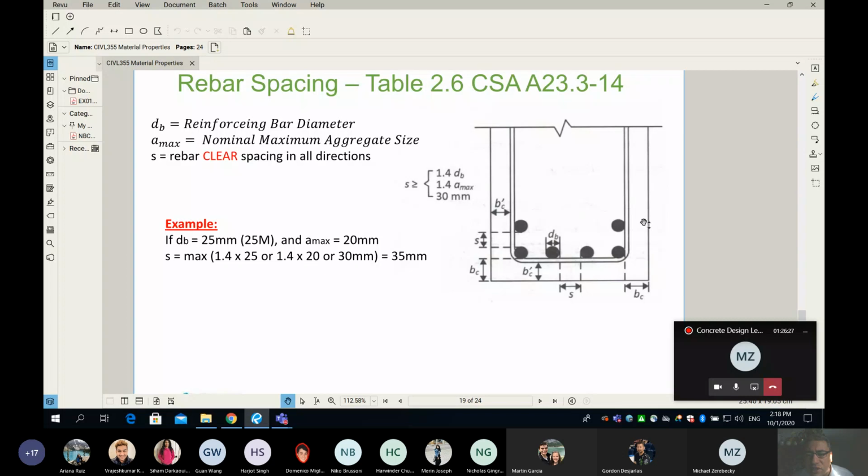When we bundle the rebar, they will not be that efficient, because concrete is not going to wrap around the entire perimeter of your rebar. That's why in our design, we have to reduce the area of those bundles. Anyway, this is advanced, it's outside my course scope, and we will never do it. We will always maintain a clear spacing between the rebar. That's it.